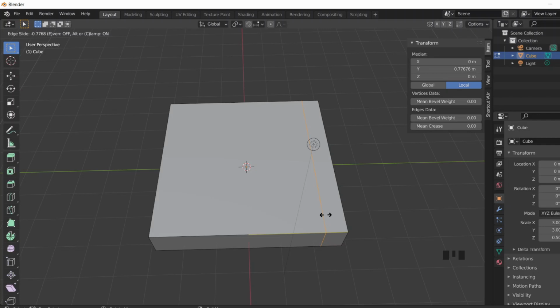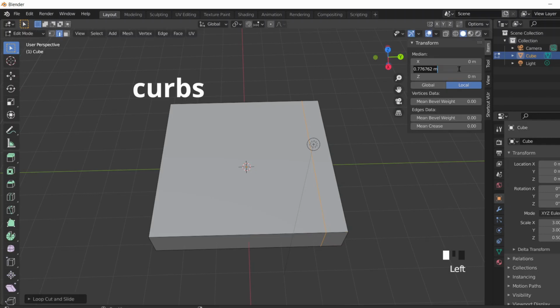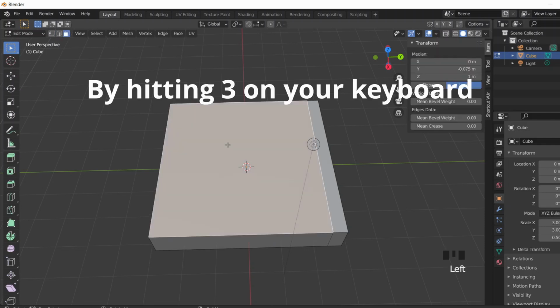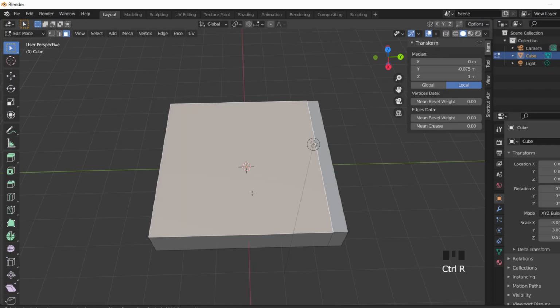And I'm creating this line such that I can add the curves of our road. So I'm going to do 0.85. And I'm going to do the same thing. I'm going to click on the face. So go on face mode, click on that, Control R, and go to a point where it can add the mesh. And then drag that to be around negative 0.85. We want to keep things as symmetric as possible. So notice the shape here is 8.5, so then that would mean this has to be negative 0.85.